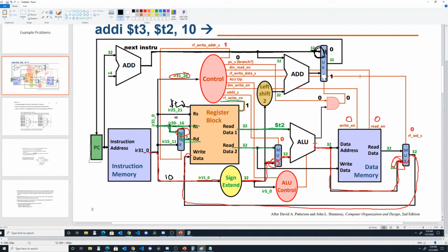Right, okay, so Max is saying this mux is the only one that breaks the convention. Okay, right. Yeah, so this is a convention. So this mux should be coded as this, because we're saying we don't need a branch, which will force this gate to 0, and we want to pick this top one. Because if we take this branch, that's going to get fed back in here, and it's going to go back to the program counter, which is going to set the next instruction.